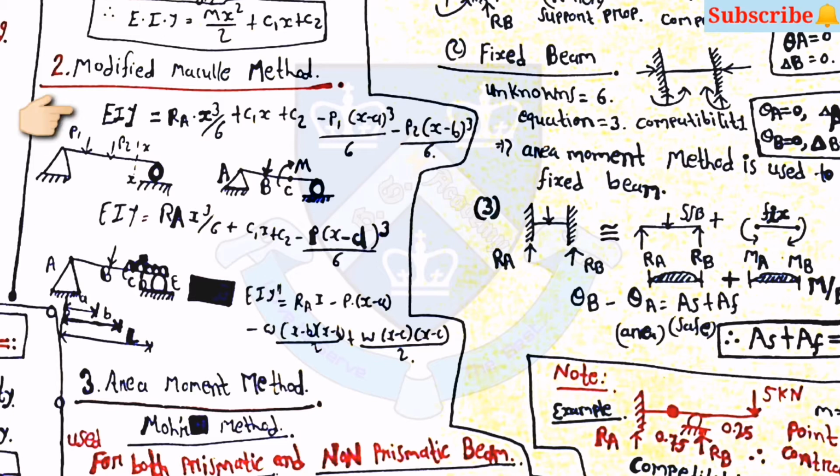Then the second one is the modified Macaulay method, in which the equation will be like E into I into y is equal to RA into x cube by 6 plus C1x plus C2 minus P1 into (x minus a) cube by 6 minus P2 into x cube by 6.